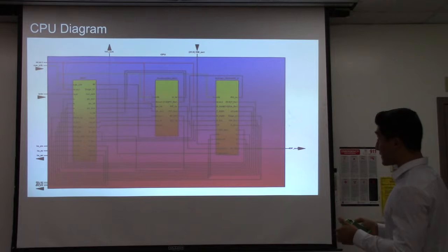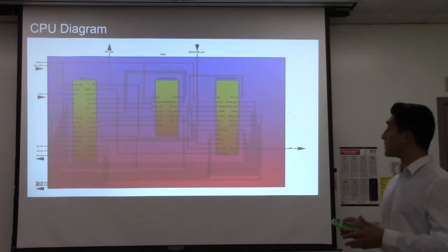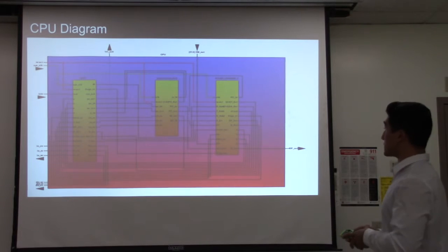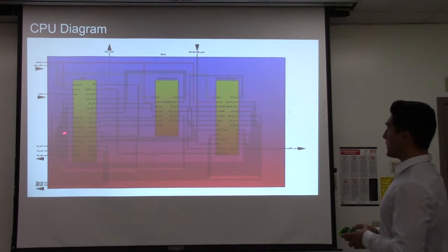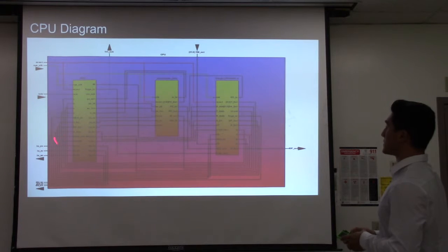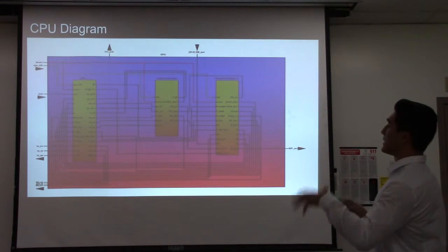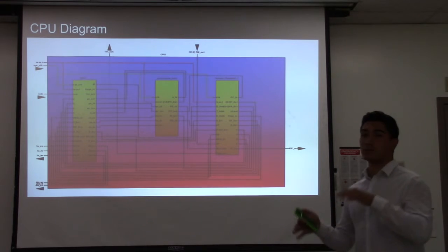That state machine varies from just a few states to up to 6 on a write back for a load instruction, because it has to access memory. So 3 to 6 clock cycles, and in each one of the states, various control words get changed.